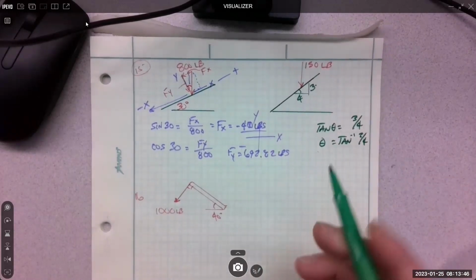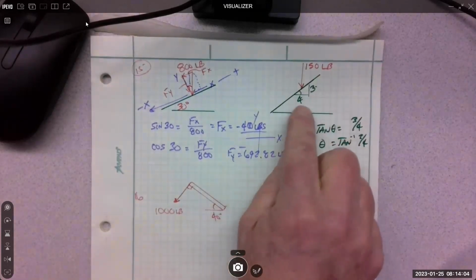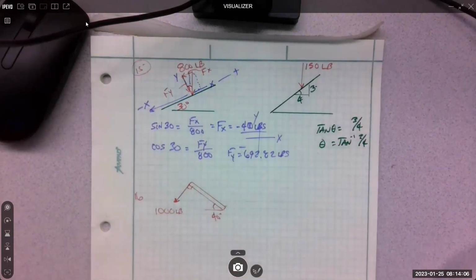Right? So this is a common notation in the civil engineering world, the land development world, and the construction world, and it's just giving you rise and run, the slope of something. So I tend to take the rise and run and just turn it into an angle and then work it normally. You can do ratios.